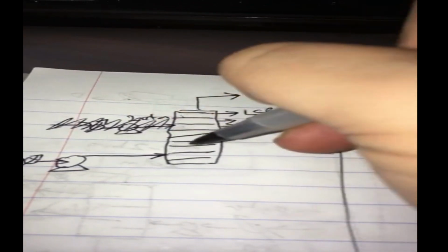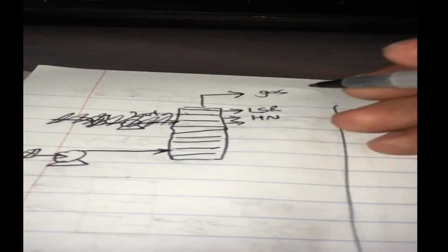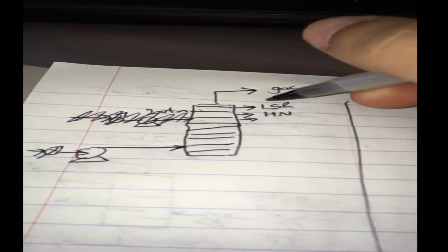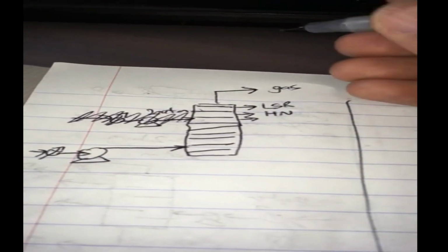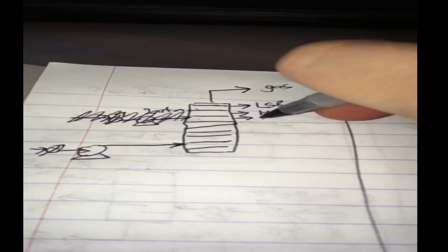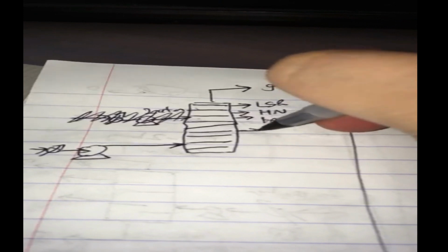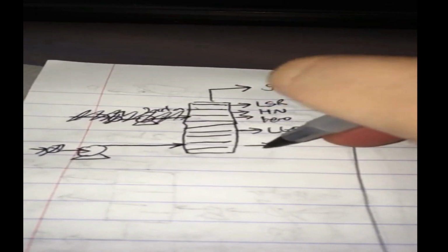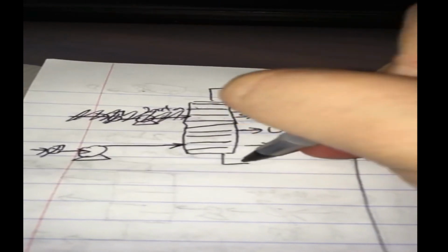And remember, crude is usually heavy, so most of it is very heavy stuff. Like you've seen the assays before, like 50% of that stuff is going to be long residue. So it makes sense to put it near the bottom rather than at the top, otherwise there's a lot of remixing that occurs. Anyway, so heavy naphtha, kero, somewhere here, light gas oil, heavy gas oil, long residue.